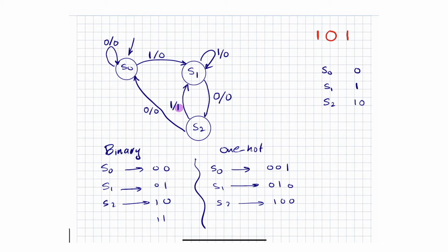Either way, it doesn't matter which one of the encoding or the state assignments you actually do. The final circuit that you're going to come up with hopefully will detect, functionally speaking, the same exact pattern of 1s and 0s, just implementations are different. And we've seen this in the analysis step now. We've seen several circuits detecting the same sequence. But anyway, for this particular implementation, I'm just going to assign it with the binary numbers. It's just because the table is going to be a lot simpler because I only have 2 flip-flops and I don't have 3 flip-flops, okay?